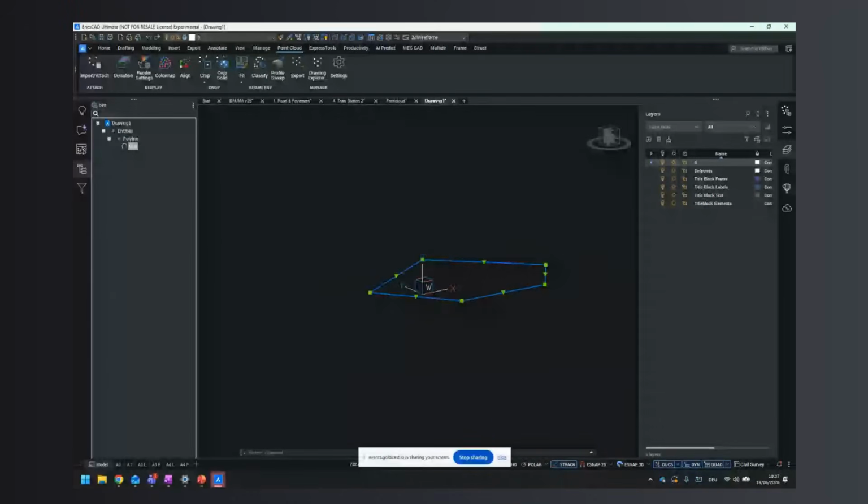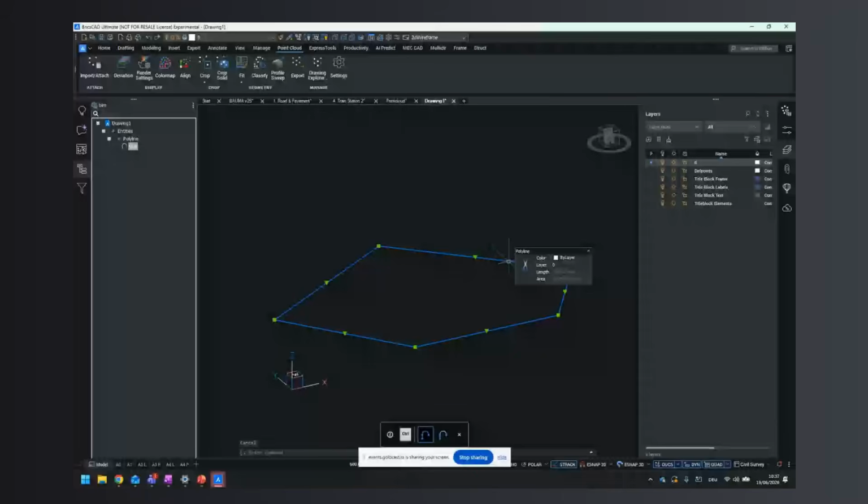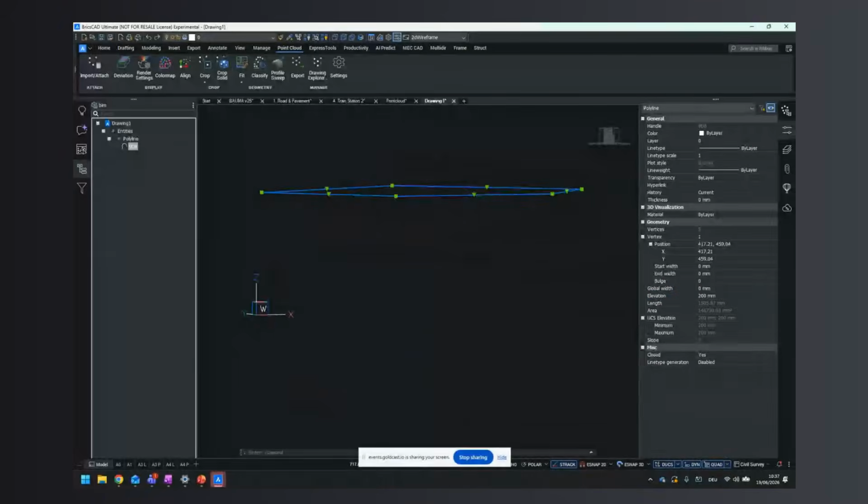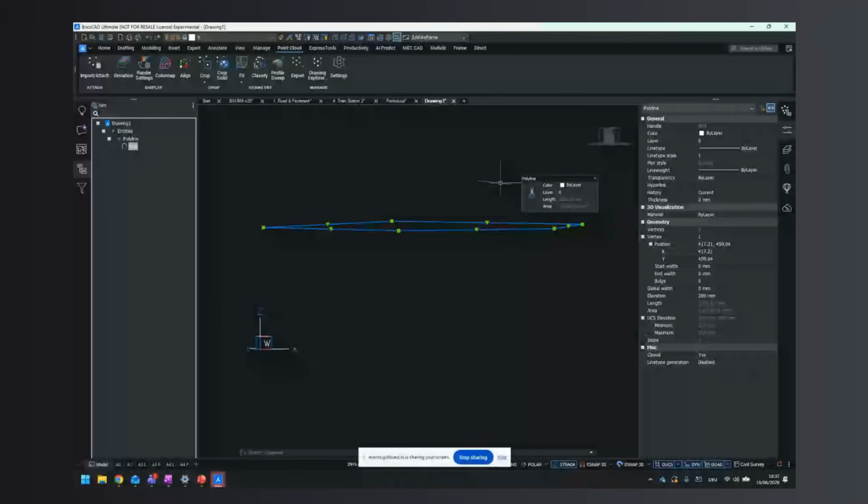So there are two legs in this question. The first leg is how to put it in the correct elevation. The answer is through the properties panel. We have an elevation section, so we can type in our elevation in millimeters or in meters, and then elevate it, right? But the second leg of the question is how to do a 3D polyline. For a 3D polyline, we need points to be at separate Z elevations.